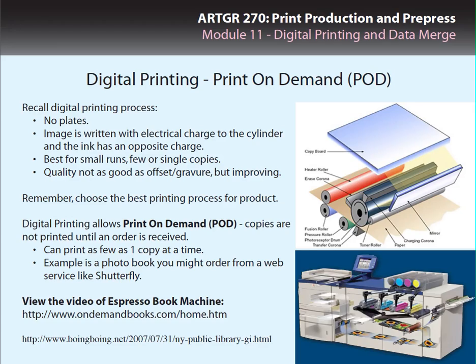Recall from the printing processes that digital printing is a process where there are no printing plates, and the image is held by an electric charge on the cylinder, and then the ink or toner is held with the opposite charge. The opposites attract and so on, and then it's transferred to the paper, and then that cylinder can be wiped clean in an instant with the electrical charge and be ready for the next image to be put onto it. So having that ability to swipe out a plate, not a plate, but an image, to change the image quickly on the run allows digital printing to print each sheet differently without having to stop the press.